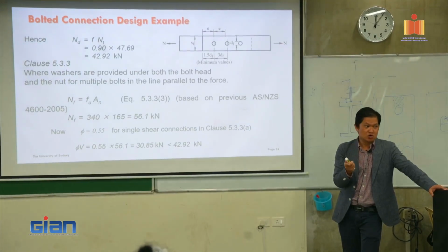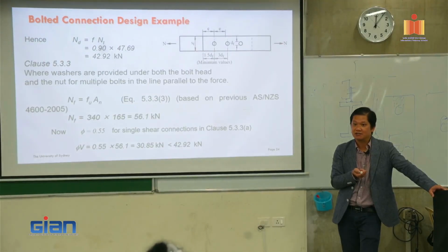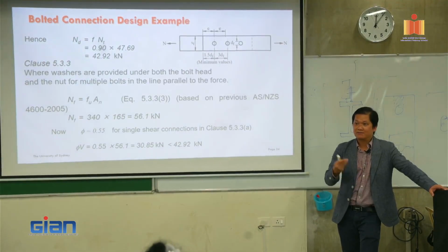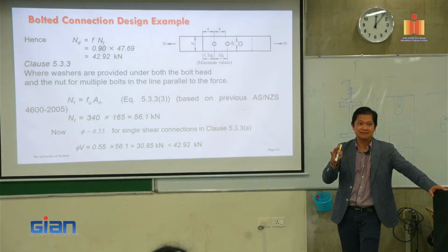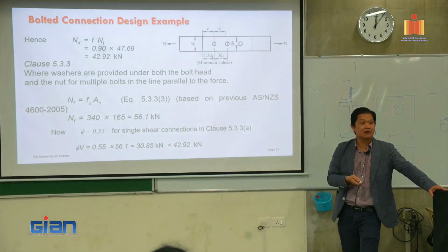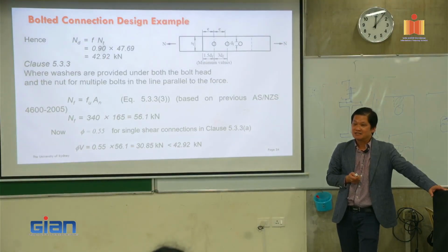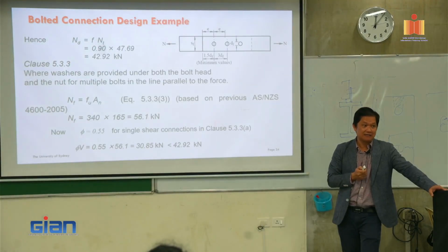Particularly for screw connections, we test a lot of them and we see a lot of variation. Normally we have to test four of them, exactly the same configuration, and they all vary, sometimes by 20%. This is not easy to understand. It depends on a lot of things. That's why when we calibrate that, the factor is low.